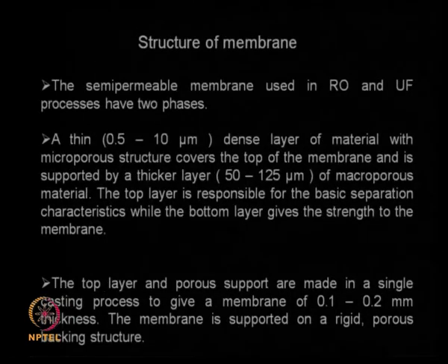Structure of membranes. The membrane will have two phases. You will have a thin dense layer of material with microporous structures, which could be about 0.5 to 10 microns. This structure covers the top of the membrane and it is supported by a thick layer, 50 to 125 microns, of